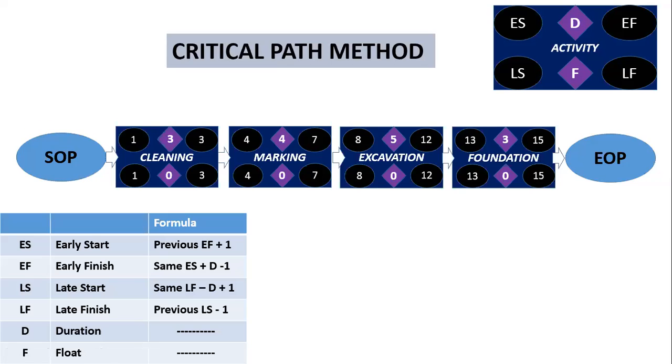What is the early finish of the final task? That is foundation, early finish 15. The same value we are copying in the late finish box. That is 15. Then what is the early start of the final task? Foundation, 13. I have copied the same thing here. We have completed the late start and late finish of the final task.